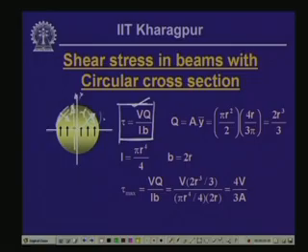So, it is very difficult to use this particular formula, or in fact this formula cannot be applied in evaluating the shear stresses in this particular zone. However, if you look at this particular position, which happens to be the neutral axis of this cross section, since along this diametral line the shearing stresses are all parallel to the y axis, we can compute the shear stress at this particular location.